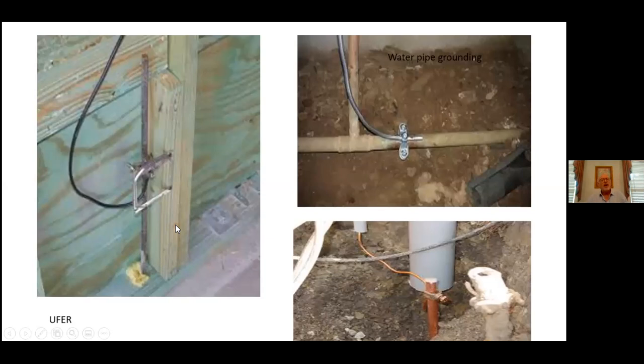The way we would locate those would be typically in a garage or some other location near the meter on the interior of the home, where it would be basically a double outlet cover that was totally blank. We would remove that cover, find that connection, photograph it and include it in our report to show where the grounding was. Not that you would ever need to go there, but we would just prove that the grounding was actually connected, and that would be good to go.